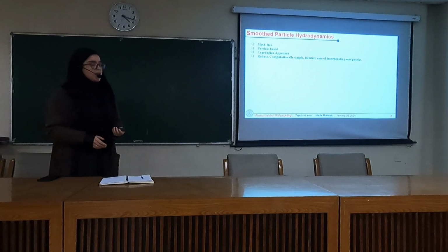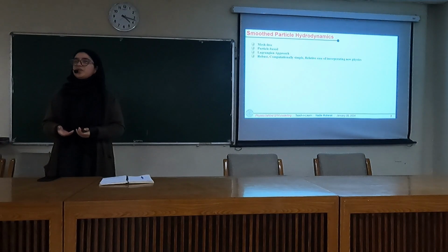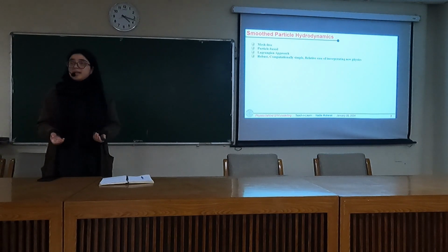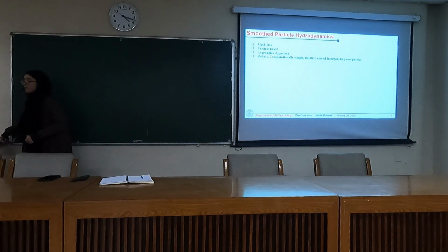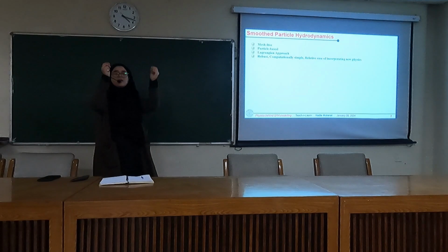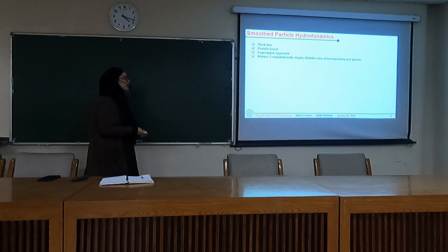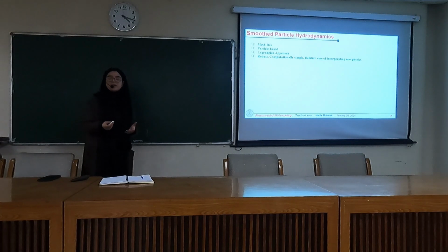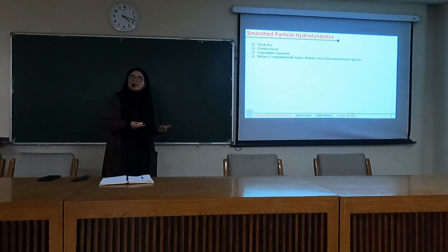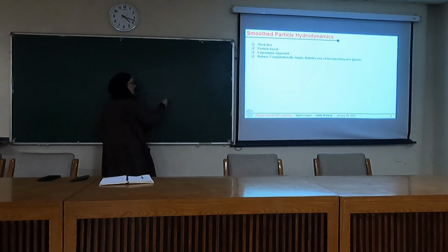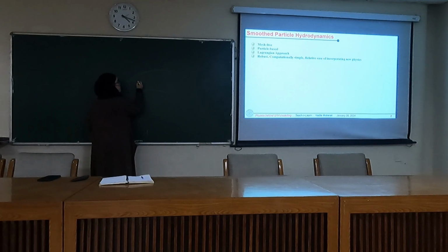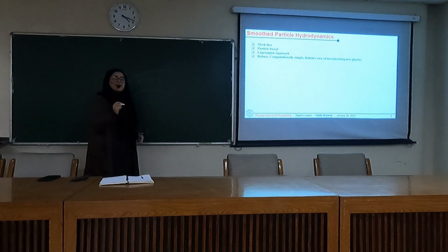Now coming to smoothed particle hydrodynamics or SPH, as I already mentioned, it's a mesh-free method. It's particle-based, and it's based on the Lagrangian approach of continuum. For those who don't know, if we want to understand fluid flow, there are two approaches that have been proposed. One is the Lagrangian approach, and another is the Eulerian approach, which have been named after the scientists that proposed them. The Lagrangian approach is like, if we have a fluid flowing, we are tracking one particle as it moves from this point to this point. We are tracking each particle.